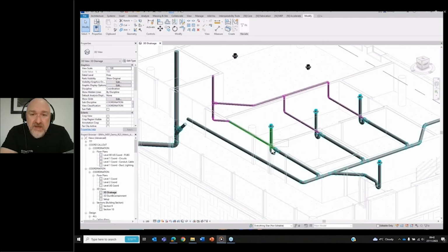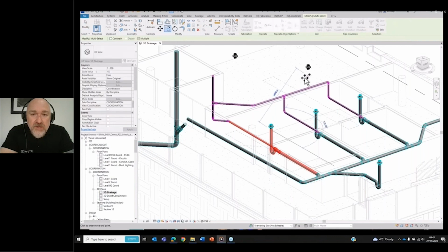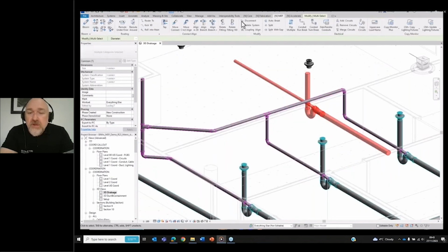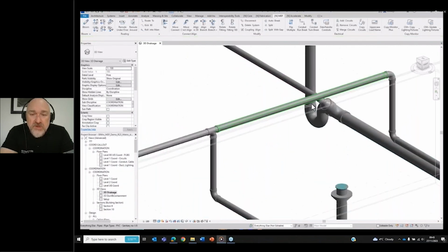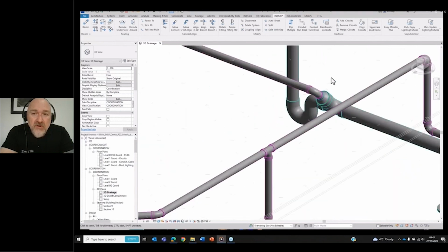What we're going to do is connect another floor drain here. So we're going to, again, just save a bit of time, copy a chunk of pipework, and then use move connect just to connect this in. Here we go. Again, what we want to do now is rotate this around so it's actually pointing towards another main run.